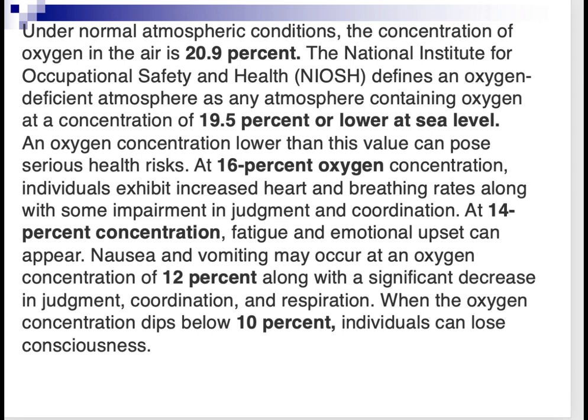And so under normal atmospheric conditions, the concentration of oxygen in the air is around 20.9%. The National Institute for Occupational Safety and Health defines an oxygen-deficient atmosphere as an atmosphere in which there's less than 19.5% oxygen. Also, when you're at less than or at 16% oxygen, this impairs your judgment. Your respiration rate may go up considerably because you're trying to bring more oxygen into the body. So your brain doesn't shut down, your heart doesn't shut down. And at 14%, you have fatigue.